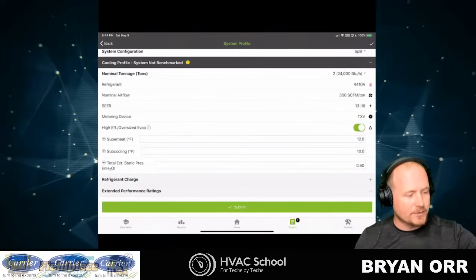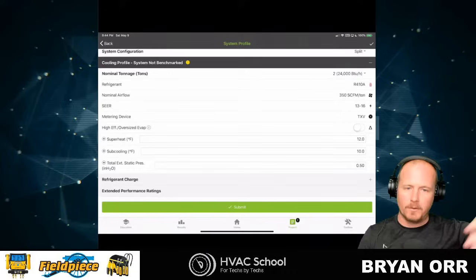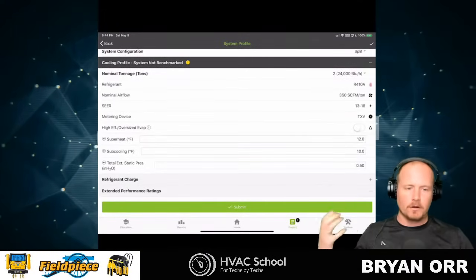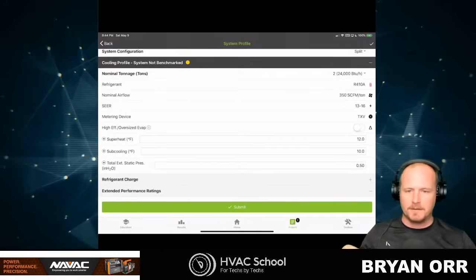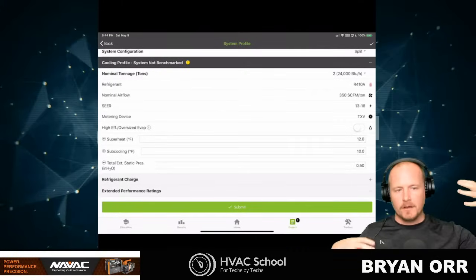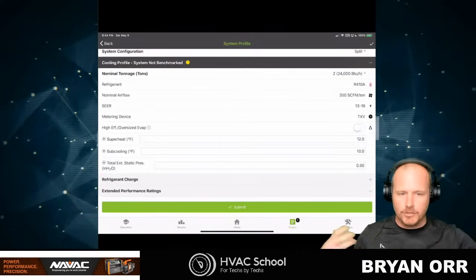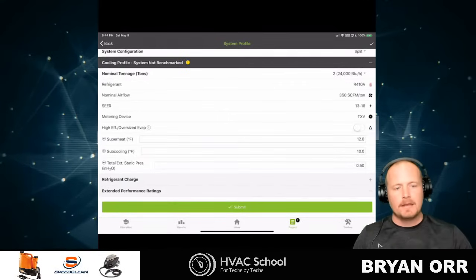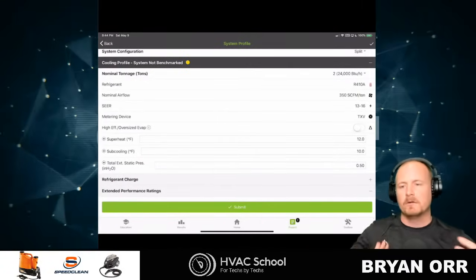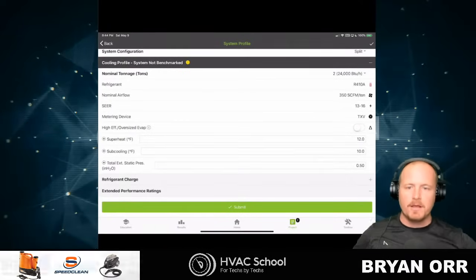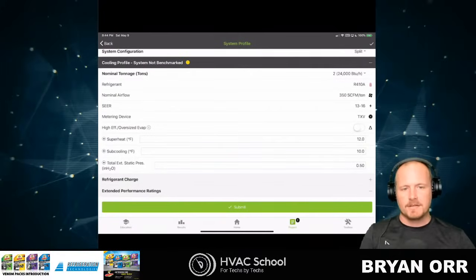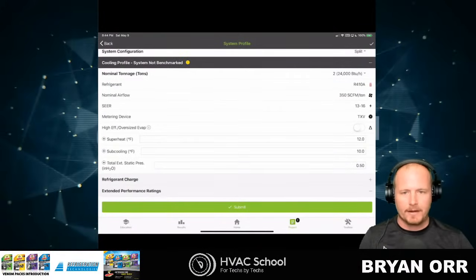All right, so below that, high efficiency evaporator coil. The way we do it at Kalos is I tell our installers when they're going to commission a piece of equipment, or we have one commissioning tech who does most of the really advanced systems, that if the coil can serve a larger tonnage, because this comes up a lot with Carrier fan coils, where you might have a fan coil that can serve multiple tonnages, if that coil can serve a larger tonnage than what it is serving evaporator coil wise, then use the high efficiency oversized evap number, and we find that to be quite accurate.